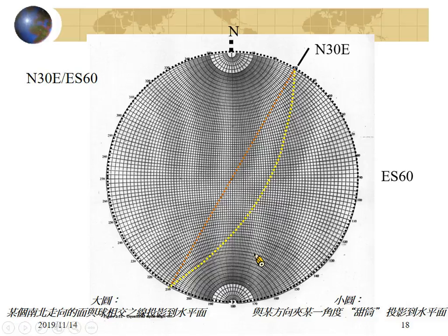Please read it. What should be the strike and dip of this first circle? What is the plane? Roughly. Please read it. So it will be north to the west, roughly 70 degrees, and dip to the southwest direction with a dip angle equal to, I think, 60 or 70. Okay?